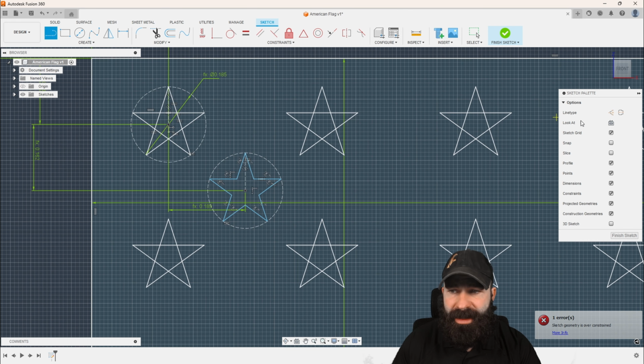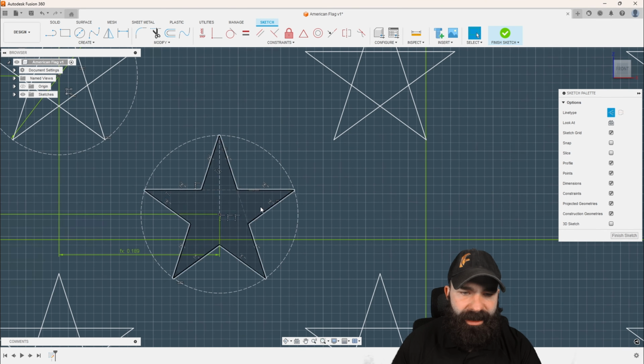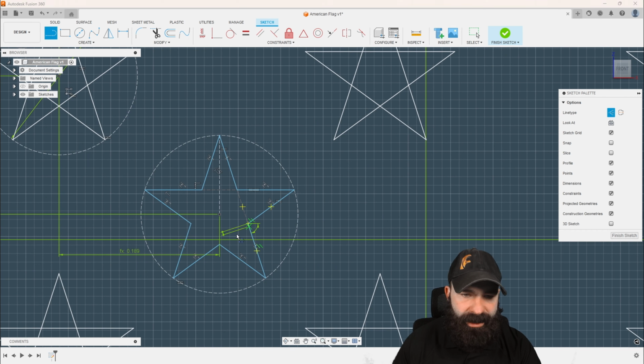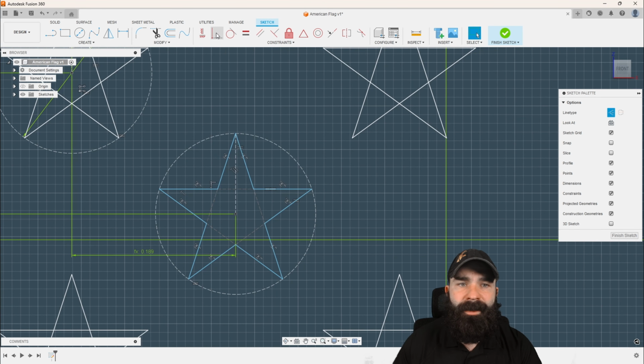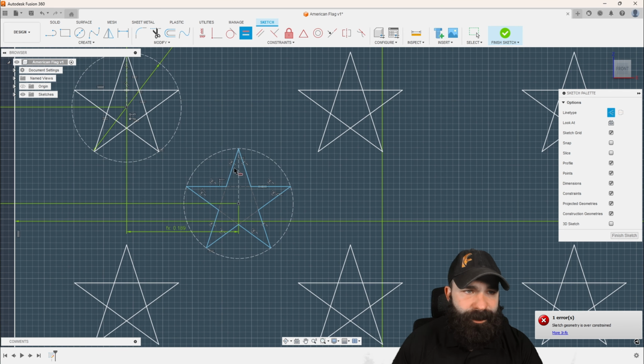So again, another way we could do this is based on a couple of construction lines, kind of fix what we've done, right? So as you're seeing me do here, I'm going through with construction lines, and I'm adding back that hexagonal shape in the middle. And what I can do with that hexagonal shape is, again, based on making all sides equal, this can actually fix and repair that shape again. So let's pattern this out.